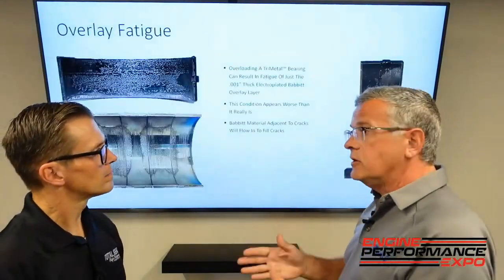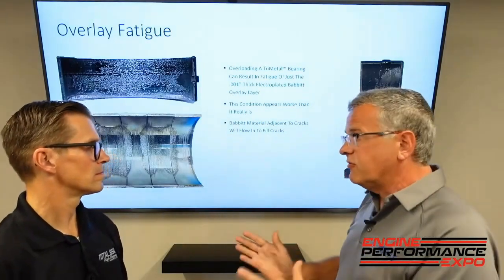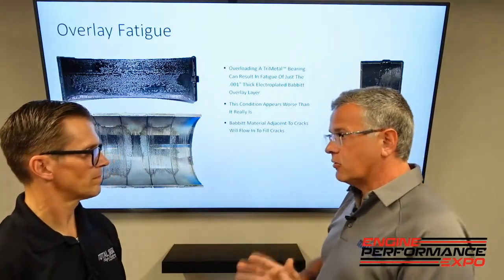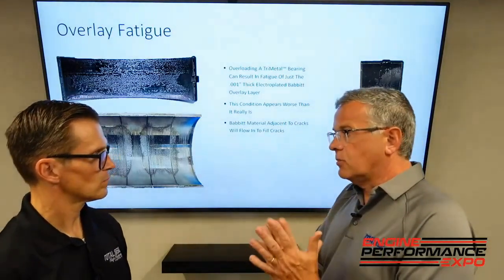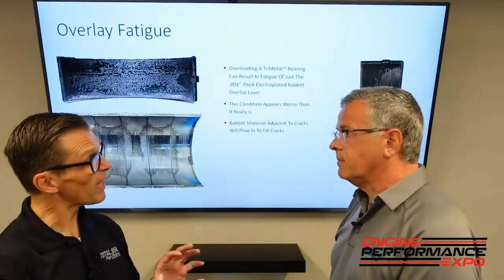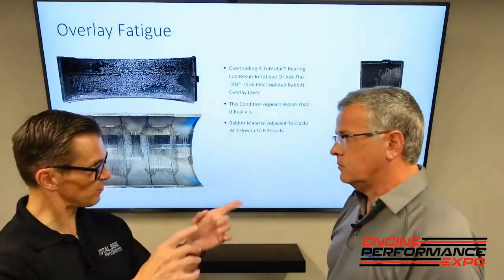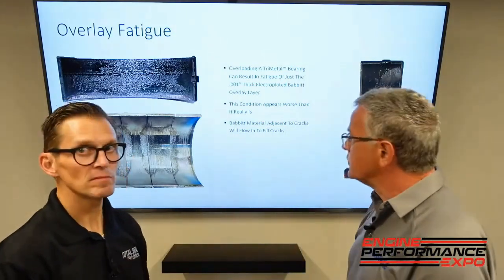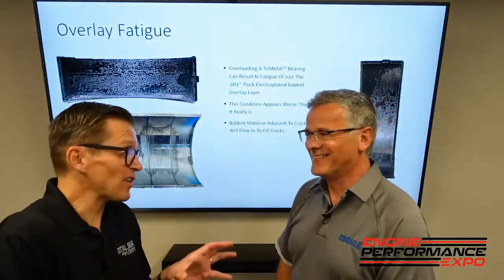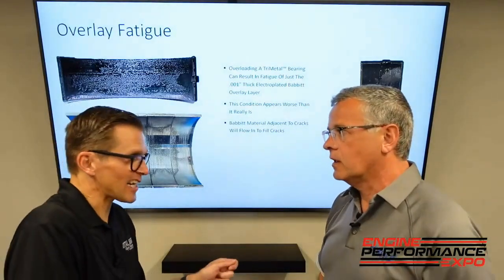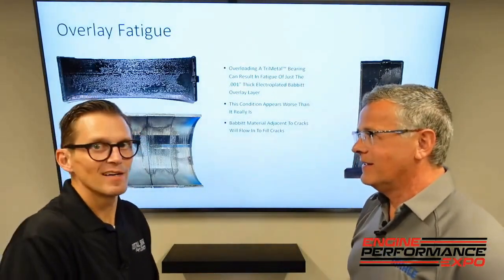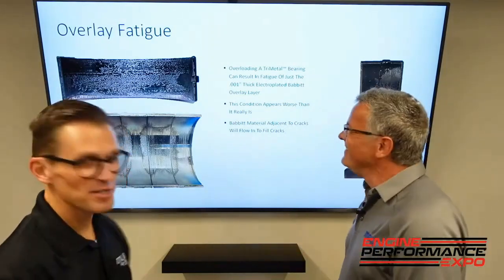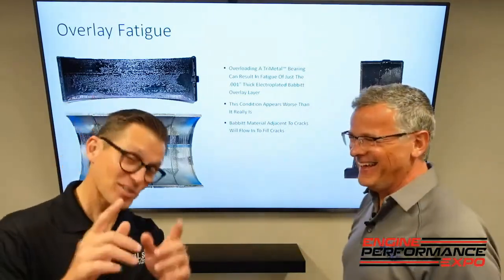Also, on a main, if you have it right up on the fillet, the crank can feel spongy. So you're typically not going to have your thrust set correctly because it's not going up against the thrust surface. You can feel that when you're checking your thrust. It'll feel a little spongy as opposed to solid because it's riding up on the radiuses. A little assembly tip there for you. If you feel that sponginess, it's not like a click, click, then maybe there's a problem. The clunk is good. Usually clunks are not good, but in this case, clunks are your friend.